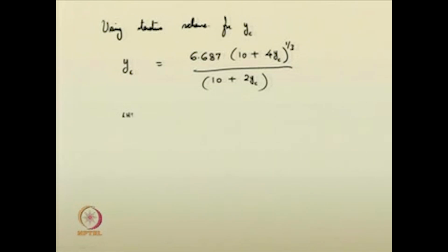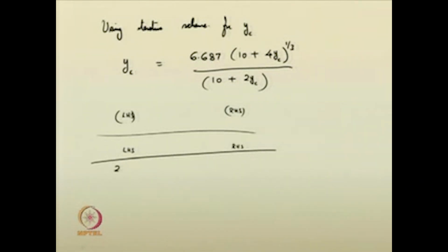So, this is the LHS of your equation, and this is the RHS of the expression. You can begin iteration, that is computation, with a known value. Take the normal depth y is equal to 2 in the computation, start with 2 and just tabulate them, LHS and RHS. I am beginning with 2 meters and the RHS of the equation is obtained as 1.252 meter.